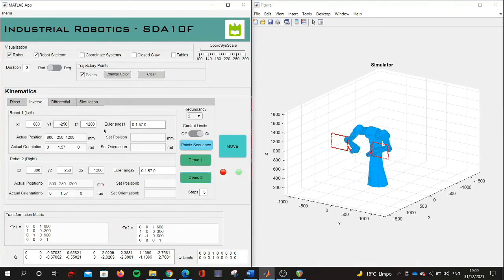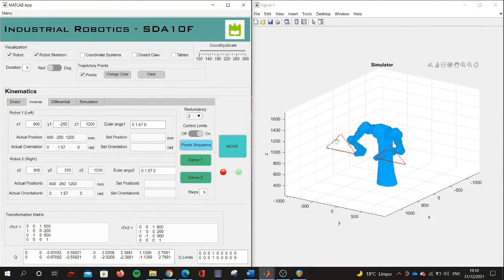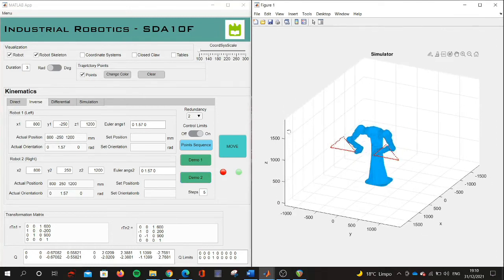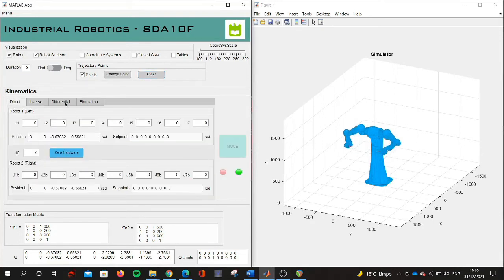The inverse of the Jacobian of the robot allows us to use linear movements. Anyways, it will introduce some error because of the variation of the rotations while using the same Jacobian for each step.